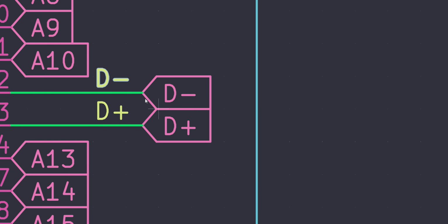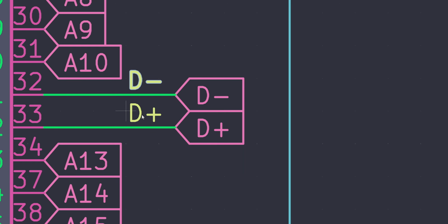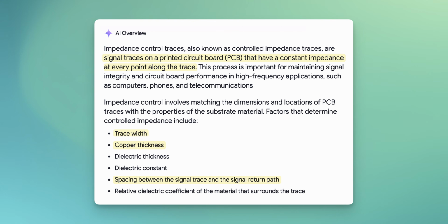And these here, these yellow ones, are actually what are known as a differential pair, because USB lines are known as what's called an impedance controlled line, meaning that they should be relatively the same distance from one another, or the same length.